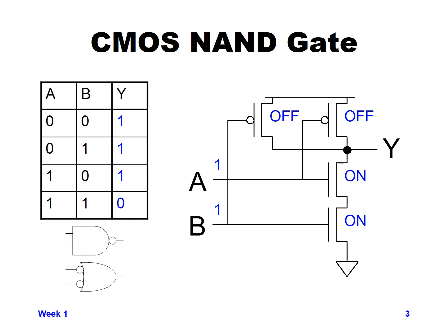So this set of transistors connected like this gives you the functionality of a NAND, which is, only if both inputs are 1, you get a 0 out. So that's a not AND.